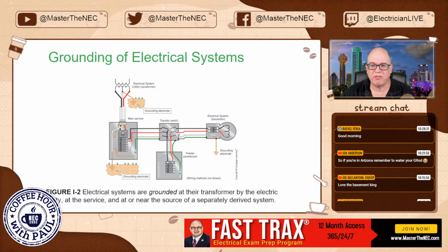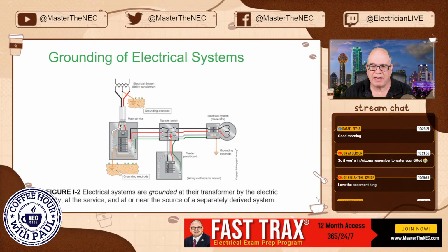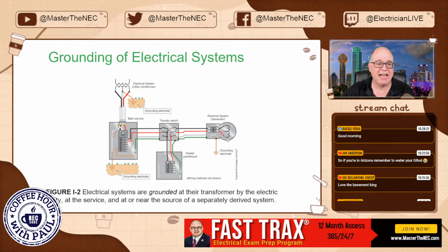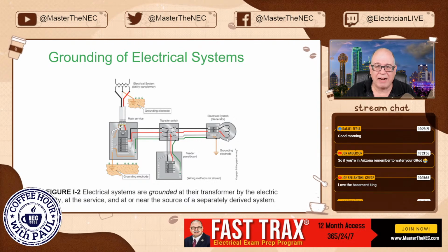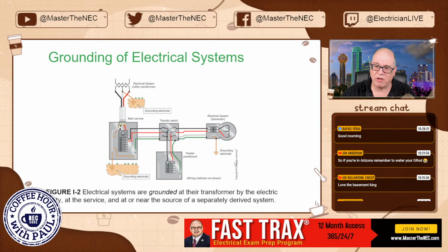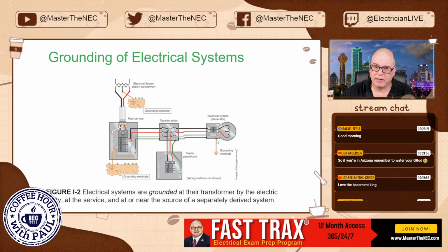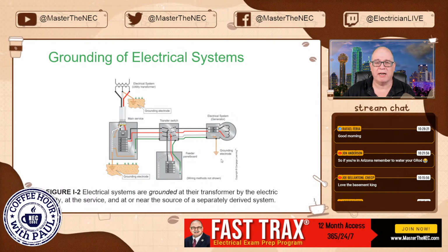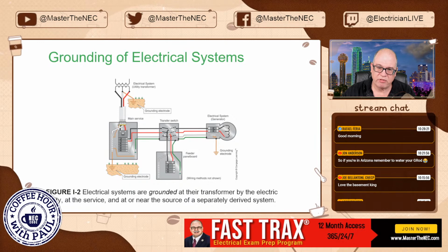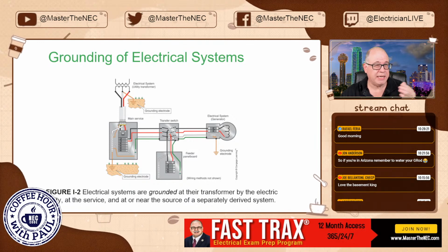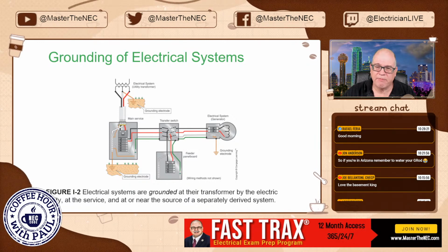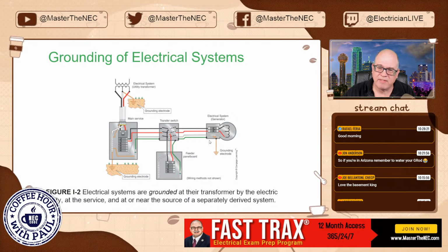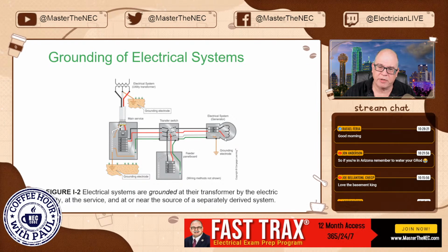And here you can see that this goes to a transfer switch, and this one is actually switching the neutral. So this happens to be a generator, but yes, it is a separately derived system, and it has its own system bonding jumper in here, because it is treated like a separately derived system and has its own grounding electrodes. If you did not switch this neutral, which is probably what you get in most residential applications, in other words, your neutrals go to a common solid bus, then this is not separately derived, and you would not put a grounding electrode out here.